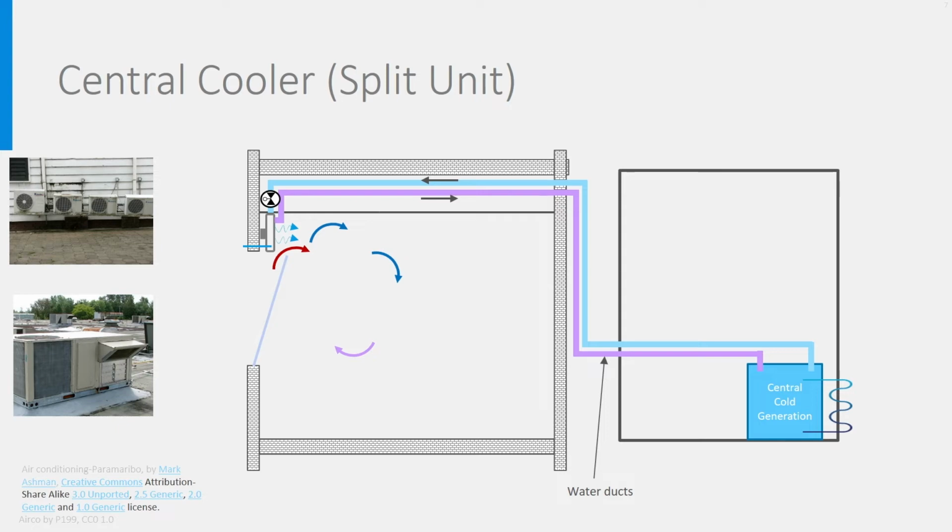It can also be a heat exchanger connected to district cooling or to a duct to the ground or a river, the sea, etc. The chilled water is brought to the room unit through piping and then returned to the chiller to be cooled again. These chilled water ducts must be properly insulated with vapor-tight insulation to avoid condensation on the pipes. In this system, natural ventilation is used, meaning that you must open the window to get enough hygienic air.